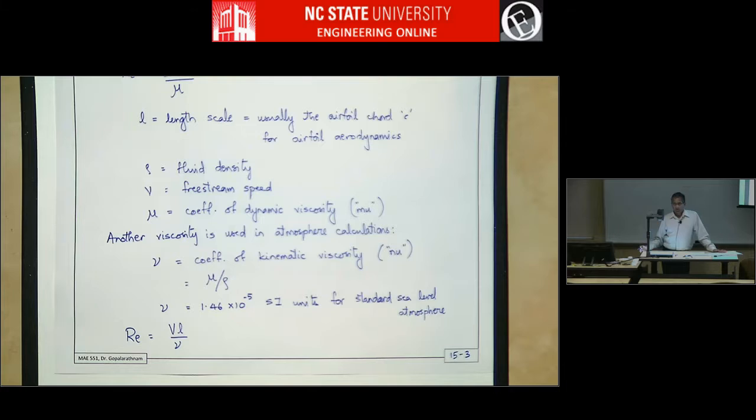So we talked about in Xfoil how you can do analysis at a given Reynolds number. That means if you calculate the drag polar, that drag polar is valid only for one lift coefficient, right? One velocity. So how do you deal with this? Because at different velocities you need different Reynolds numbers, and that means you have to calculate the drag polar over and over again.